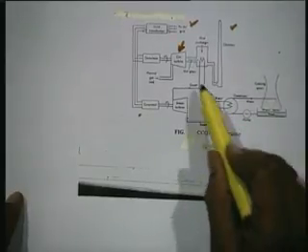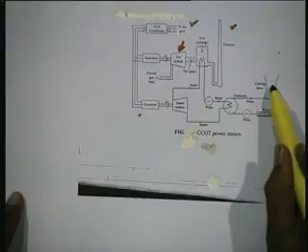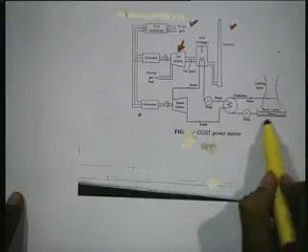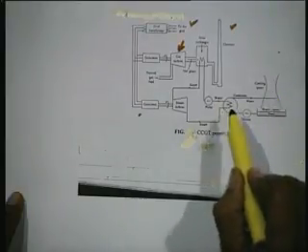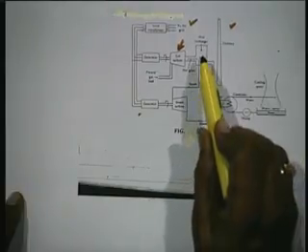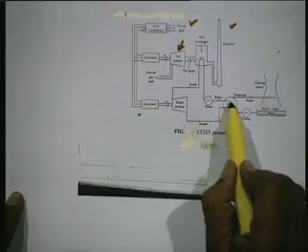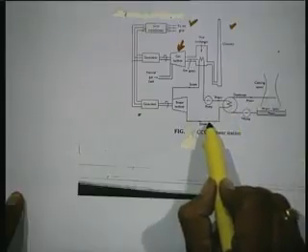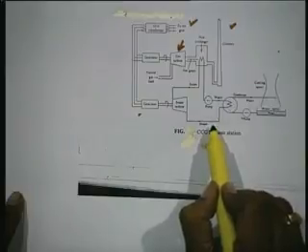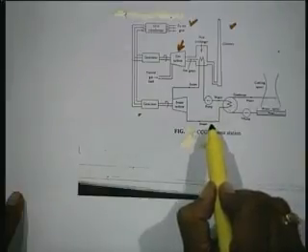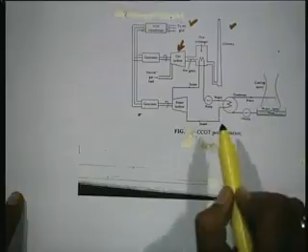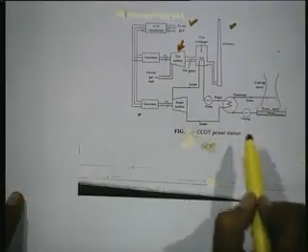and there is a cooling tower here, there is a pump here, and the water goes back, forms steam, comes back, and the steam comes here again. Again you can use this steam for cogeneration, the third dimension you can add, but I do not want to add it here to make it more complicated, because the aim is to explain the combined cycle gas turbine power station.